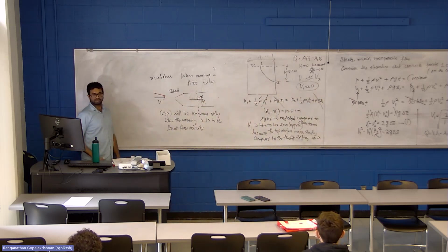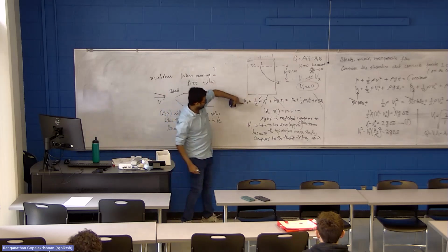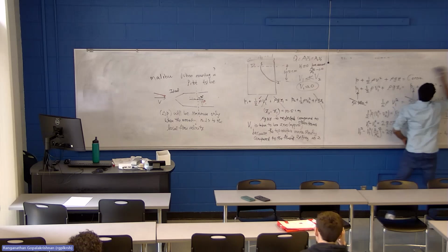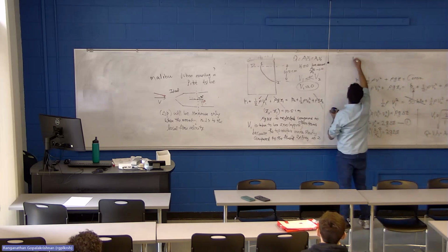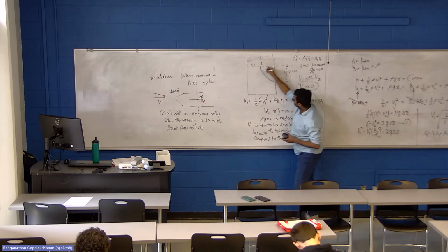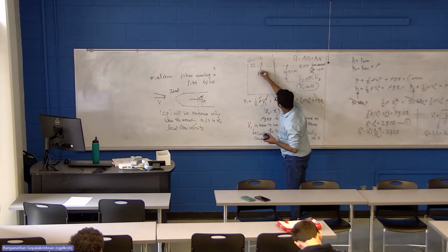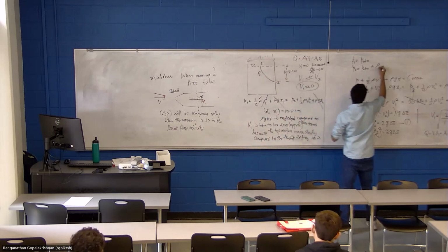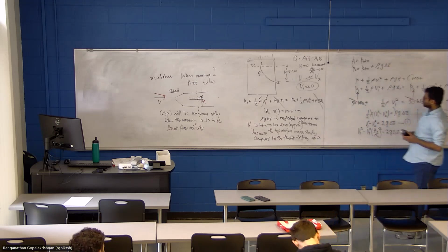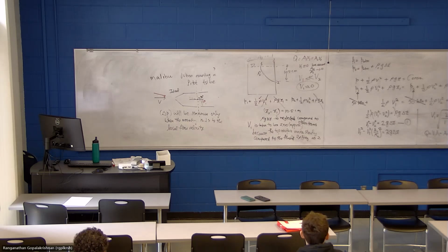That would be the atmosphere, right? And P1 would be atmospheric. Here we come to that. I need to pick up pace. P1 will be atmospheric pressure and P2 would be atmospheric pressure plus the density of the fluid here, which I think is some oil, so we call it rho naught, rho naught G delta Z.